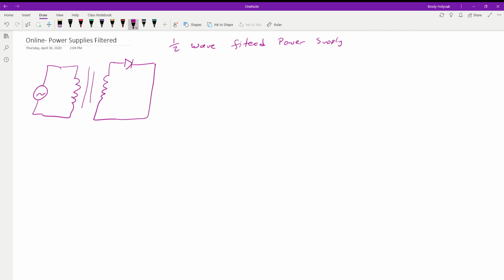This is going to come up. Our signal ground is right here. And then coming out of our output, we're going to go through a capacitor. And then we have our load in parallel with the capacitor. So again, assuming 4-to-1 on our transformers, we're going to have the 120 volts RMS, 60 hertz. And now this frequency is going to be a little bit more important, so that's one of the things we'll have to keep track of.